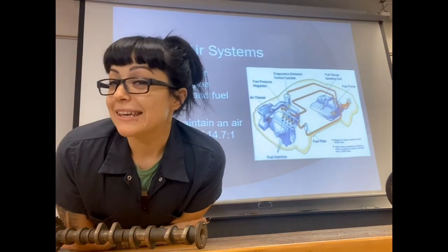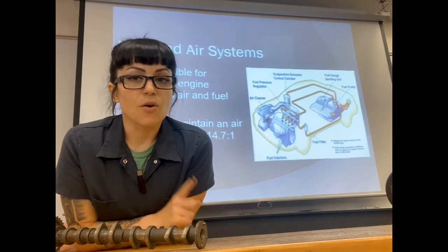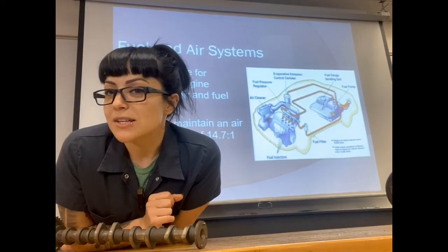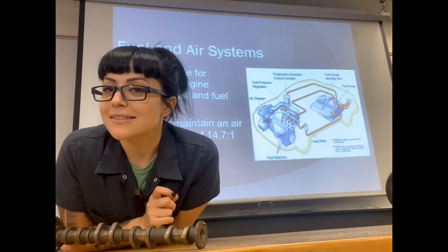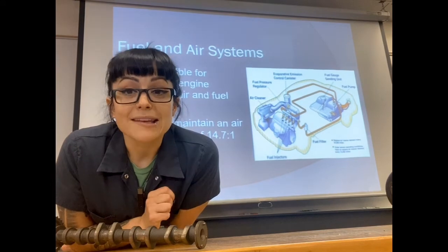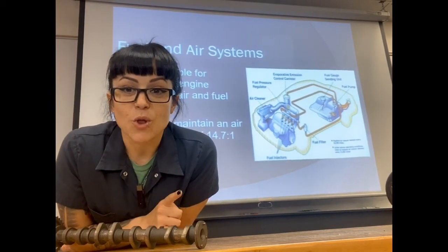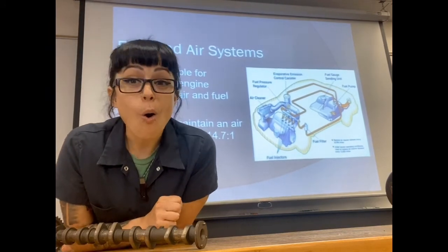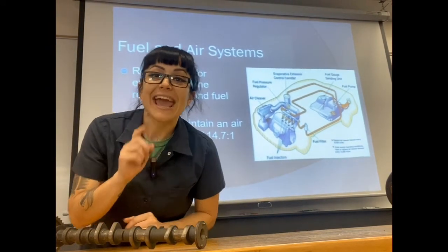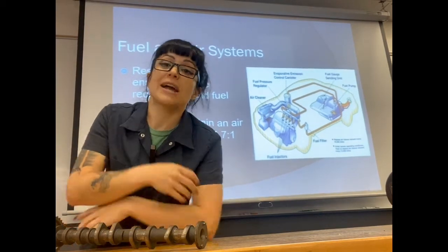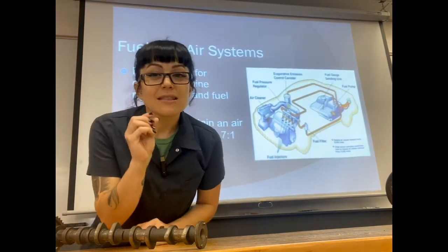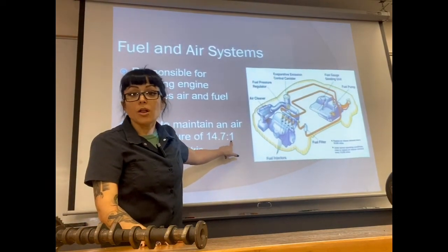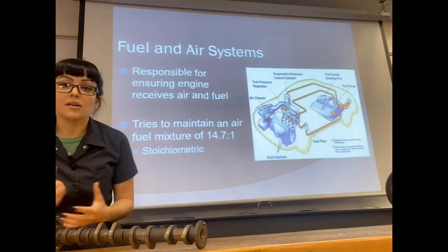If you were going to guess 14.7 or 1, which one is your air and which one is your fuel? Think about that for a second. Which one would you guess? Well, if you guess that 14.7 is your fuel and 1 is your air, that is incorrect. That would be a whole lot of fuel to 1 air, and that's not how our engines work. In fact, they work with a whole lot of air and a little bit of fuel. So that means to every 1 part of fuel, we have 14.7 parts of air,